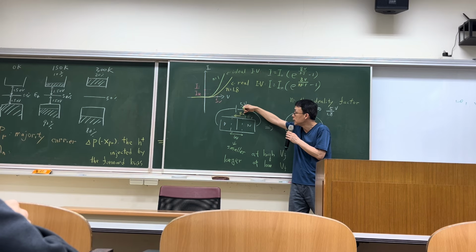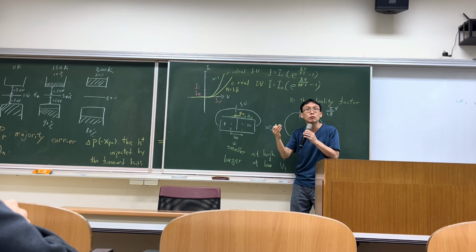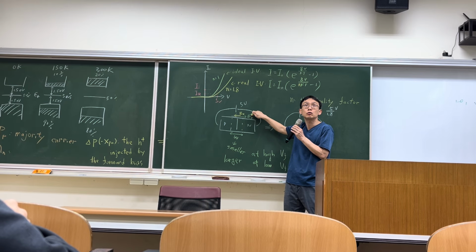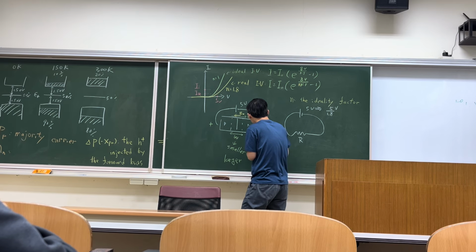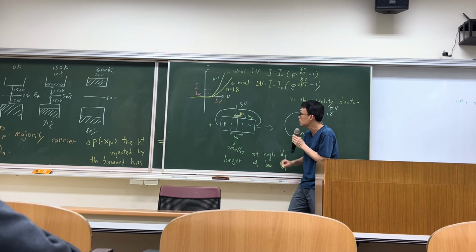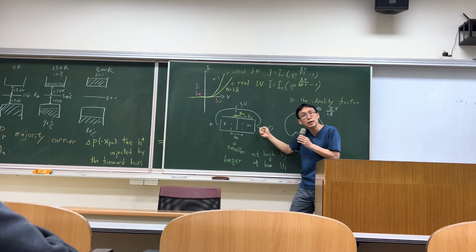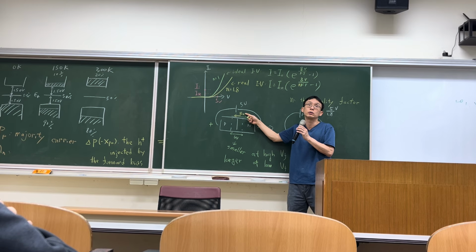This yellow E0 refers to the electrical field without any applied bias, the internal electrical field without bias. This green EF is the electrical field due to the forward bias, where you have the positive terminal connected to here and the negative terminal connected to here. So you can see the electrical field is in the direction from the positive terminal to the negative terminal, opposite to the internal electrical field due to the space charge.